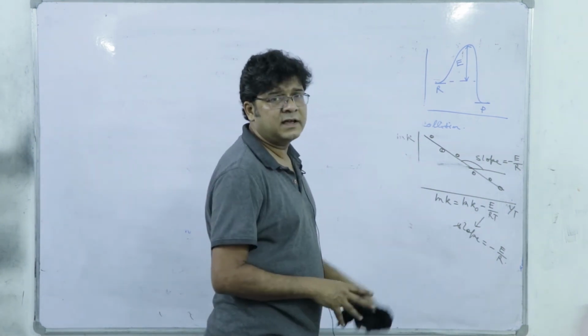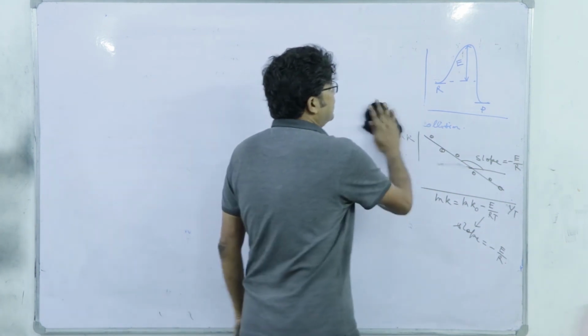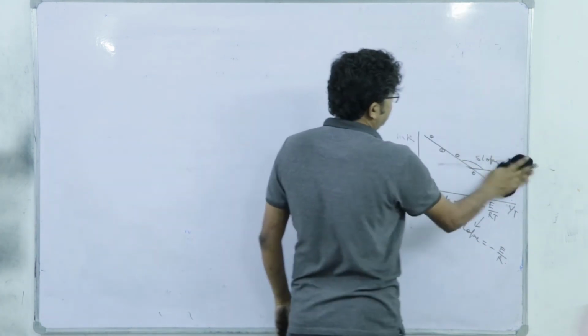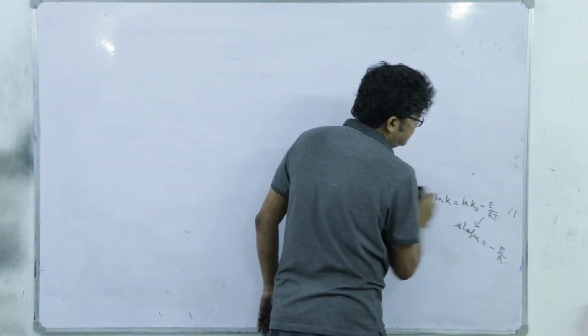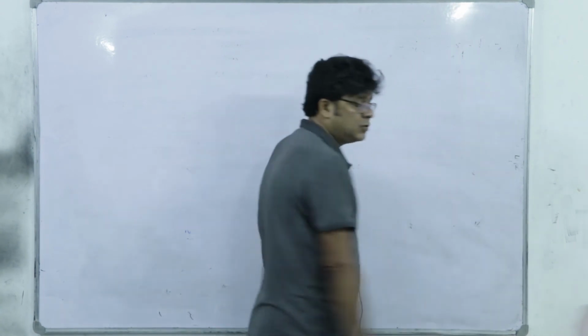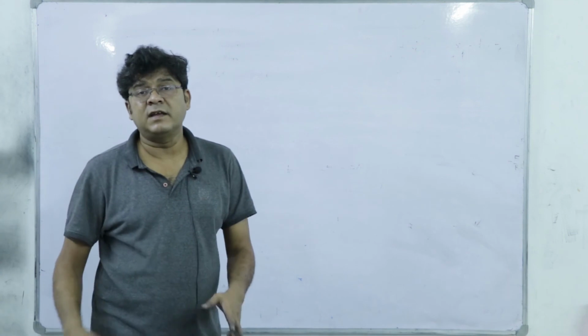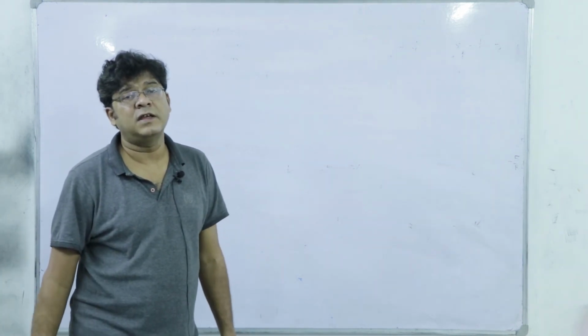Once the rate equation is available, next we can go for designing the reactor. So, this interpretation of batch reactor data does not mean our focus is to design a batch reactor, but rather to derive the rate equation which will be further utilized in the design of an actual continuous flow reactor.